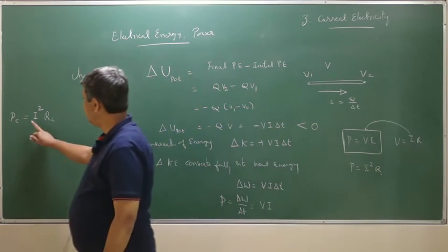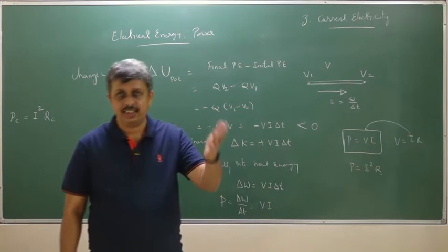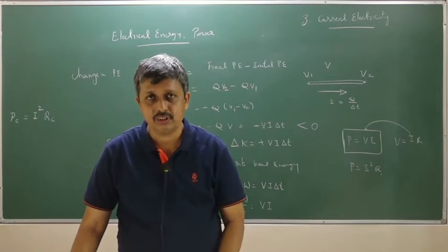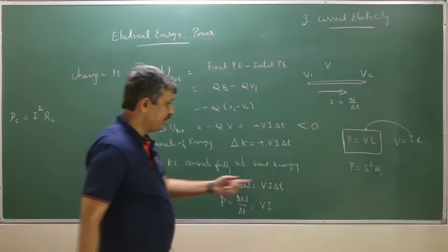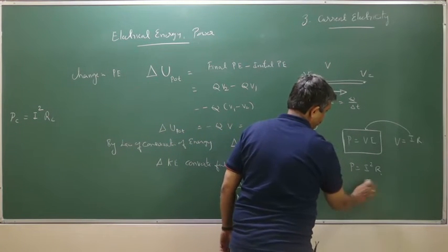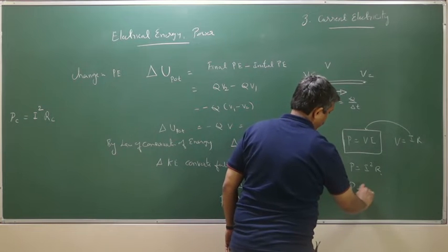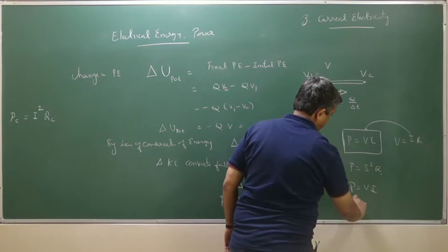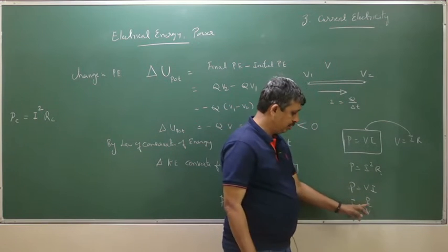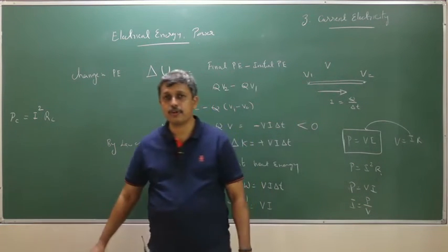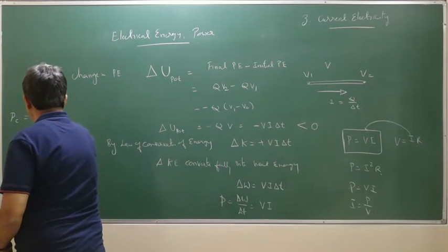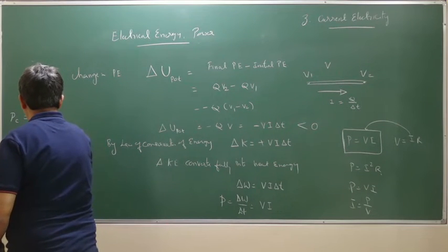So, what is this I? This I is the total current, and it is for the total power delivered, including the power delivered to your homes. Let us say the total power delivered is P. Then P is equal to VI, and hence I is equal to P by V, right? Total power delivered divided by total voltage. I substitute that here, which gives P square by V square into RC.